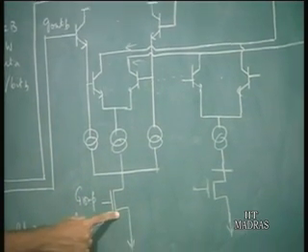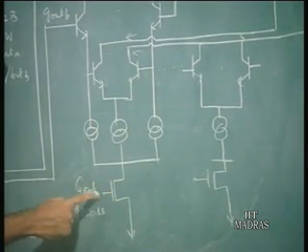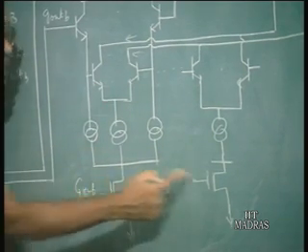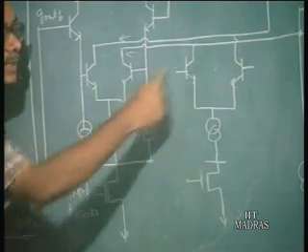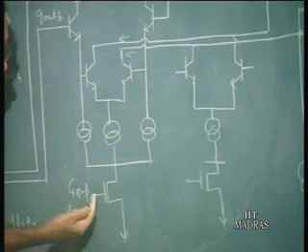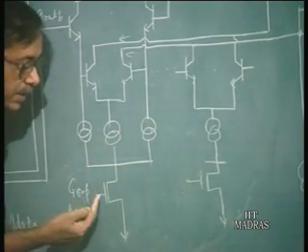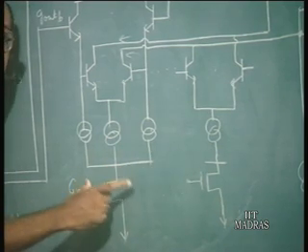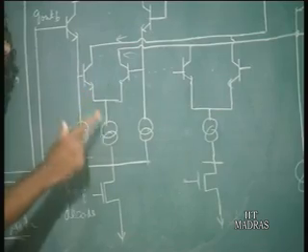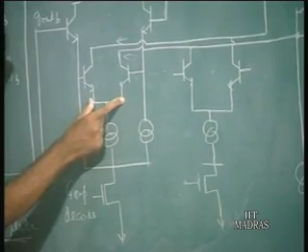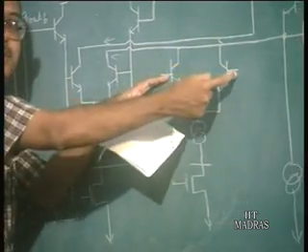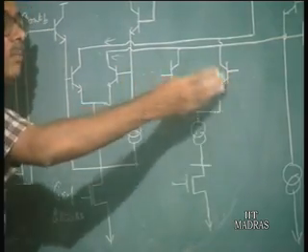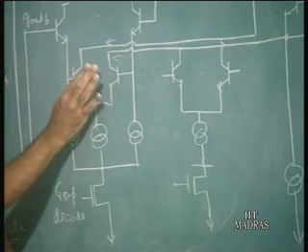Now, if you look at this circuit, for this particular differential amplifier you have an NMOS transistor. Only when this NMOS transistor is on can a current flow. So, you have 2 to the power 11 such groups here, and another output of the decoder is going to select only one out of these 2 to the power 11 differential amplifiers. So, although you have a voltage difference at the bases of these two transistors for all these transistors, only one of these differential amplifiers is going to conduct.